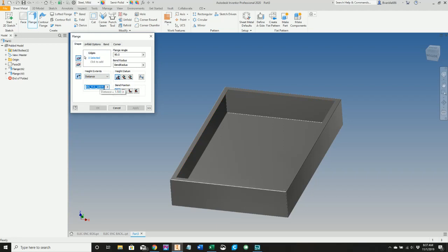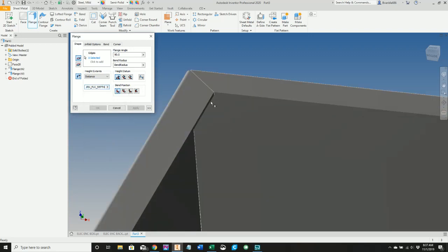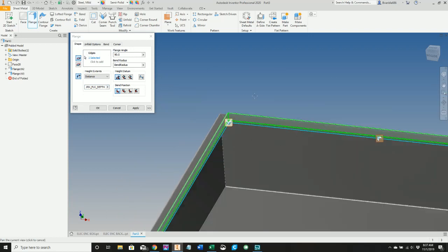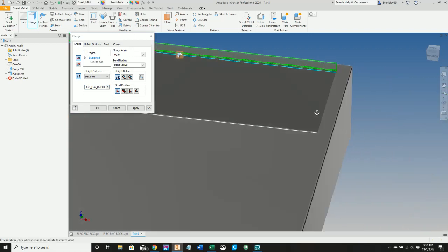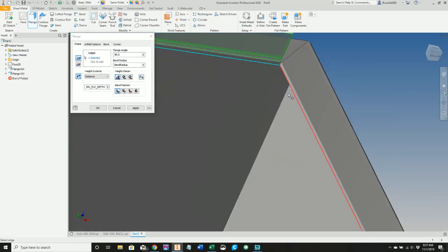So I highlighted over the top of the depth of the return flange. I'm going to go into list parameters, and this time I want to click on return flange depth and pick on, oh, got to come up here, pick on the edges, pick on that one, just wander around the outside perimeter. Make sure you're consistent.